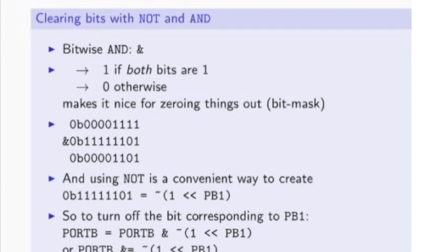And so what that's doing is it's taking whatever was in PORTB, zeroing out that one bit, and then writing it back into PORTB. And this is, again, the way the registers look like regular variables. And then the shorthand for this, of course, is that something equals something AND something can be shorthanded to AND-equals. And this is what you're going to see. This bottom line is what you're going to see in the majority of everyone's code when you look at C.